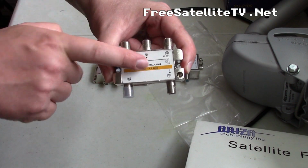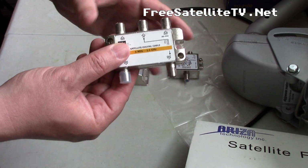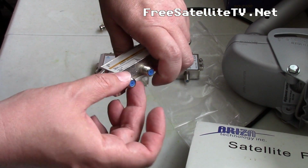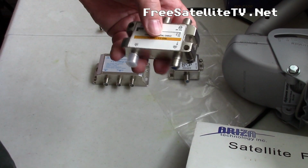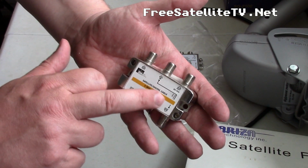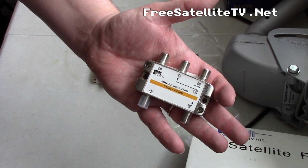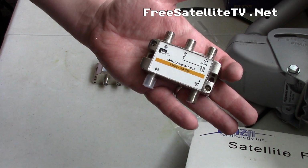A lot of the receivers now don't have a loop out option. What you're able to do with some of the older receivers is they would have 2 outputs, or a loop out, one of these connections, and you can run a cable from that all the way to another room to another receiver. So if you wanted to run satellites in multiple rooms, get one of these. This one here is how you want to connect it to that main port, so it'll switch your polarity, because your receiver will automatically switch from vertical to horizontal on the LNB.